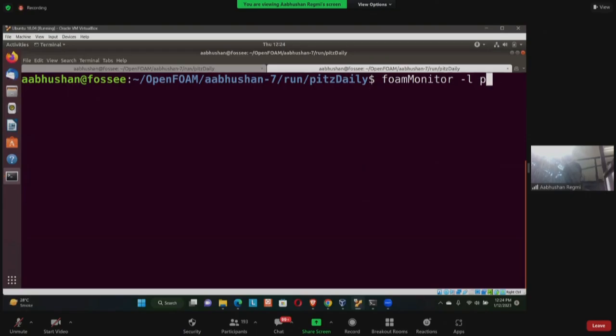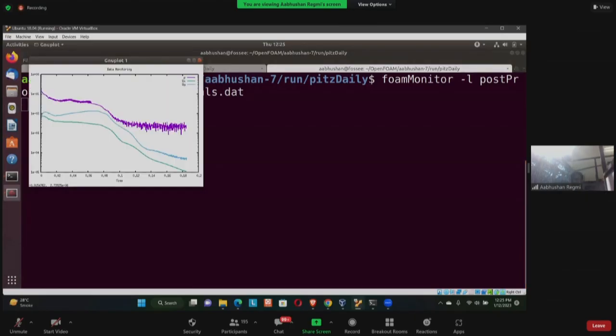Now I'm going to type postProcessing and then residuals. Here we have only one file after another file, so if I just press tab, it will complete the command for me. I'm just pressing tab, not typing anything. And finally, we get to residuals.dat. Then I'm going to press enter. So these are the values of residuals.